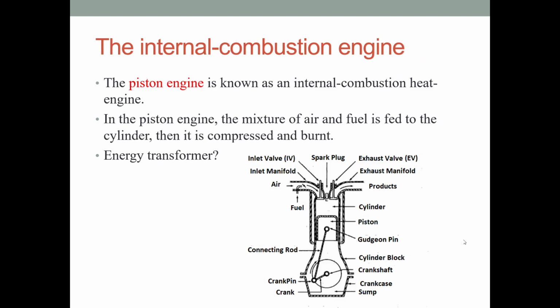So let's talk about the internal combustion engine quickly, so that you can understand what an internal combustion engine is. The internal combustion engine, also defined as a piston engine, refers to an internal combustion heat engine where a mixture of air and fuel is introduced into the cylinder, compressed, and then ignited. The piston movement in an engine is converted into rotary motion using a connecting rod and a crankshaft.